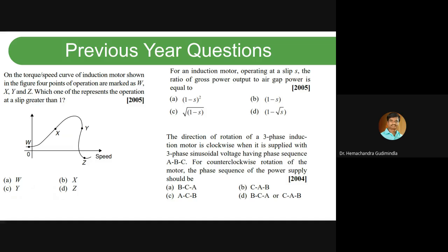If I want to change the direction of rotation of the rotor, we can change the phase sequence of any two phases but not all three. So the phase sequence is ABC, ABC, ABC. Let us take now BCA. Here it is BCA in this direction only.